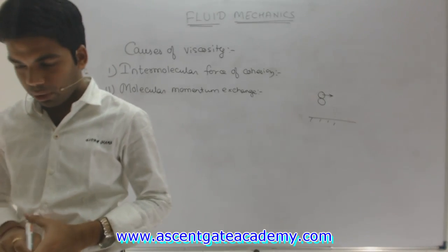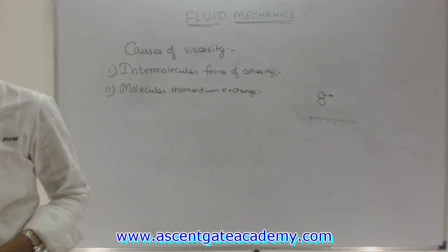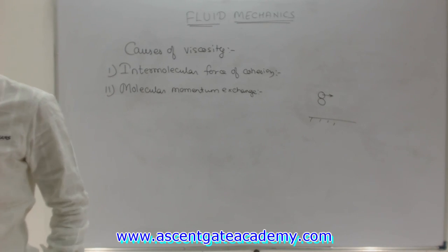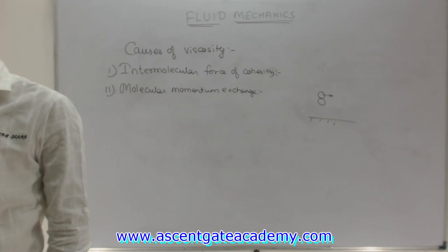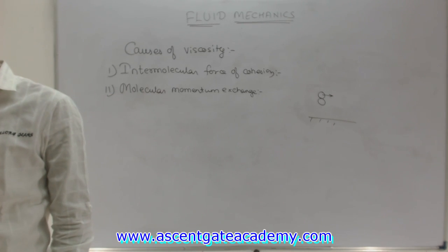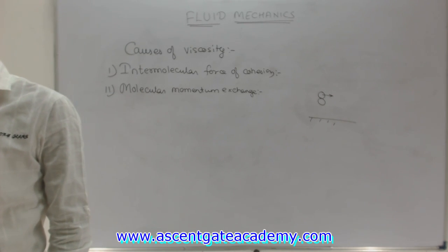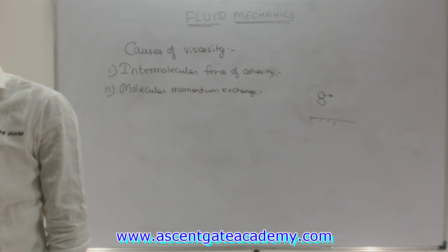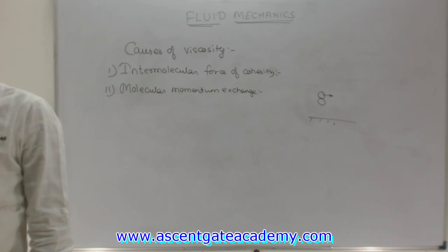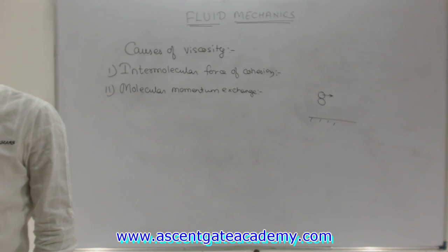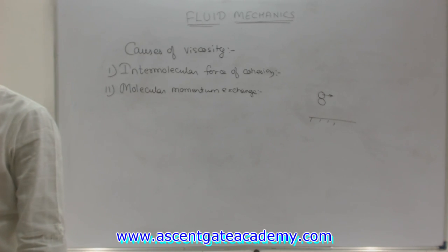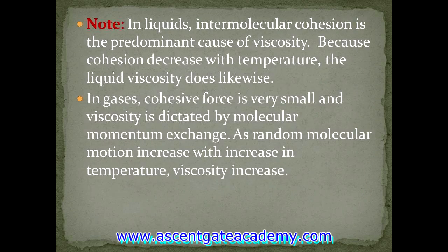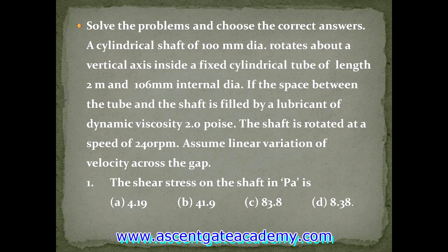So here is a very important note. In liquids, intermolecular cohesion is the predominant cause of viscosity. Therefore, since cohesion decreases with temperature, the liquid viscosity does likewise. In gases, cohesive force is very small and viscosity is dictated by molecular momentum exchange. As random molecular motion increases with increase in temperature, viscosity also increases. Now let us solve one question.